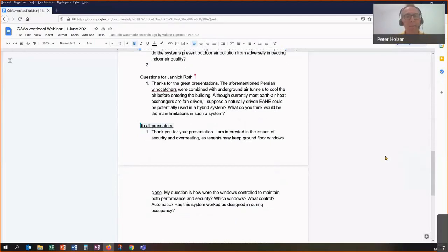And we made the experience that it could be a good idea to allow a kind of shortcut, because there are times when the earth tube heat exchanger is already warm, and then the temperature outside drops and you might have the benefit to have the air directly in your house because it's already cooler, and you might not necessarily want the air from the already warm heat exchanger being pulled into your house.